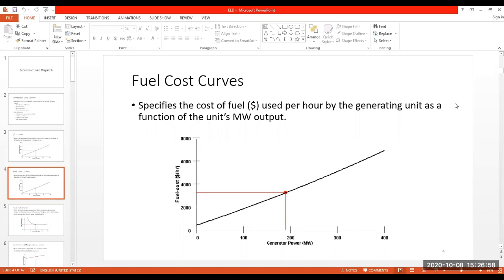You can't solve it in the same way as we did, because the cost curve is not there, but there should be some other constraints or cost functions which you will target to minimize or maximize, or optimize, I should say, to solve the economic load dispatch problem. This is if you have a power station built purely of hydro units.